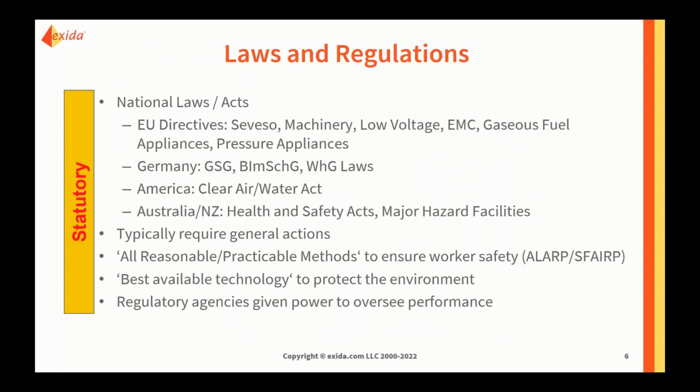Now, layer of protection analysis and actually even the entire safety life cycle itself are good engineering practices which sit underneath whatever laws and regulations exist in the environment where we're practicing functional safety. And those national laws, acts, and codes, they have priority. They are what is required. And the safety life cycle and the layer of protection analysis techniques are things that we can use to demonstrate and ensure that we are indeed meeting those requirements.